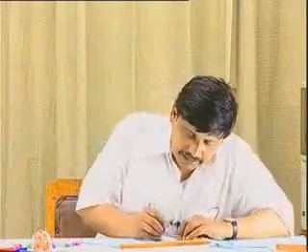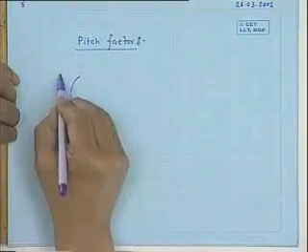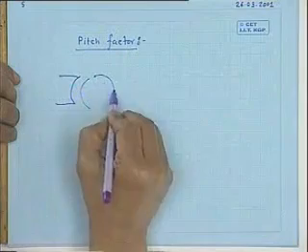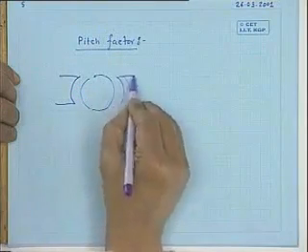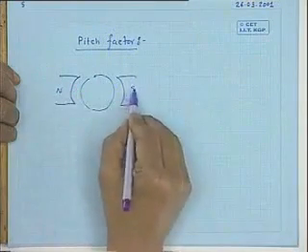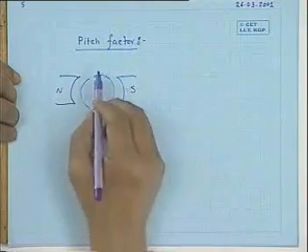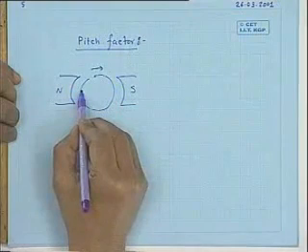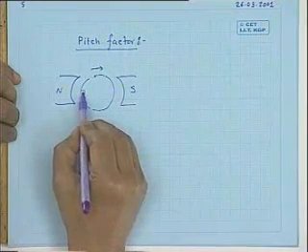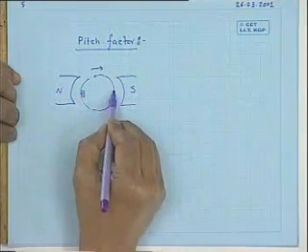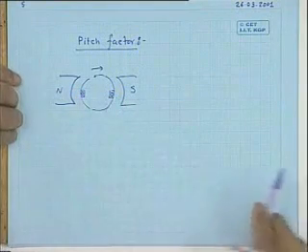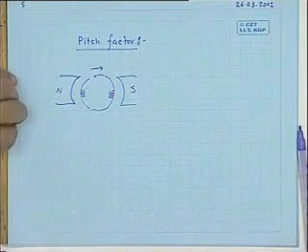Now, suppose I have a coil like this. Let us put the problem this way. This is a machine, and suppose the B distribution is stationary in space while the rotor is rotating. Generally I put full pitched coils: here one coil side, and the other coil side should be here. That is what I was telling you so far.